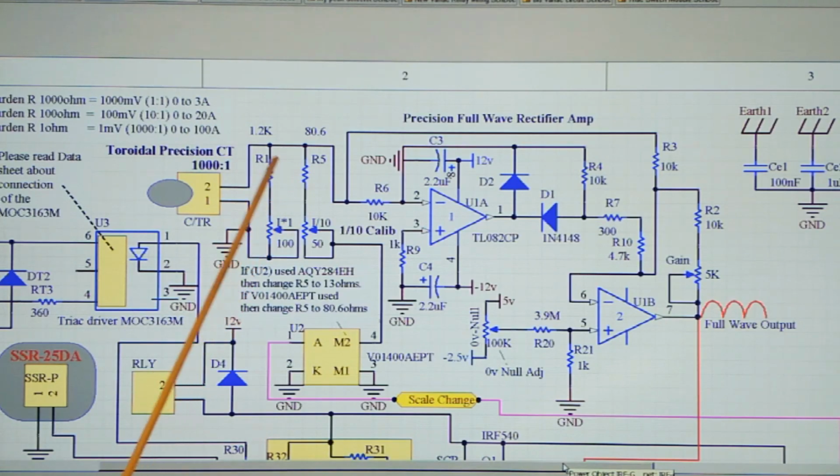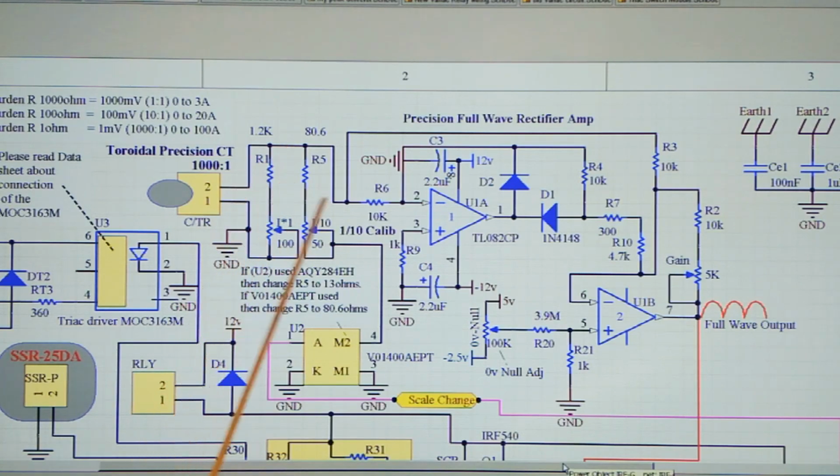With a true RMS meter hooked up to this point, I found that it wasn't exactly 10 millivolts. Now, even if it's not 10 millivolts, you can adjust to 10 millivolts with the gain on the output. So you get 10 millivolts here anyway. That's where in actual effect we do need the 10 millivolts. But for precision, I wanted the input to be exactly the same as well.